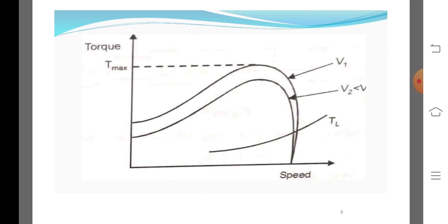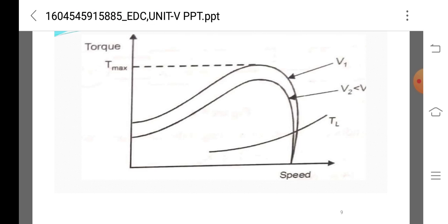This is a graphical representation. Frequency manipulation appears to be an effective method for speed control, and requires a simple DC to AC converter with variable switching intervals by means of solid state control.